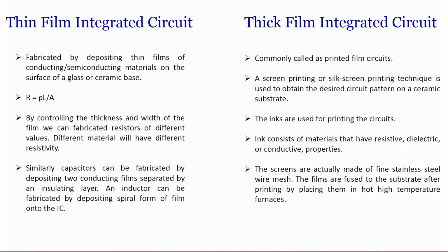In case of thick film technology, it is commonly called printed film circuits, where a screen printing or silk screen printing technique is used to obtain the desired circuit pattern. Now, the inks are used for printing the circuit, that means the ink can have resistive, dielectric or conductive properties, right, and the screens are generally made of stainless steel with wire mesh.